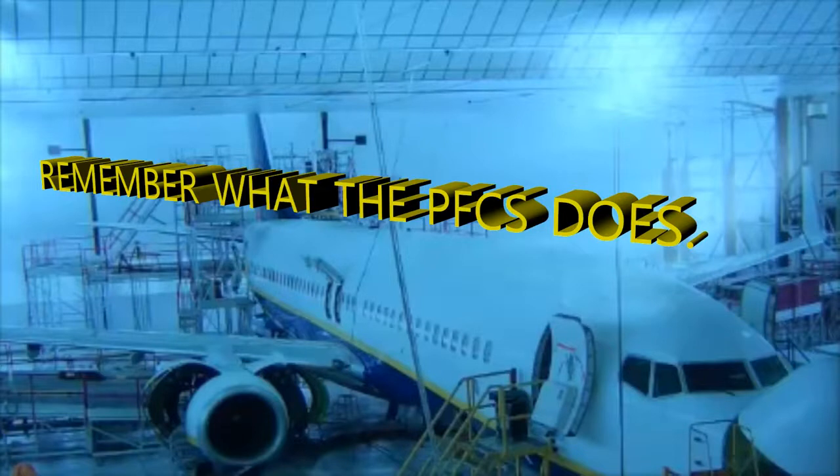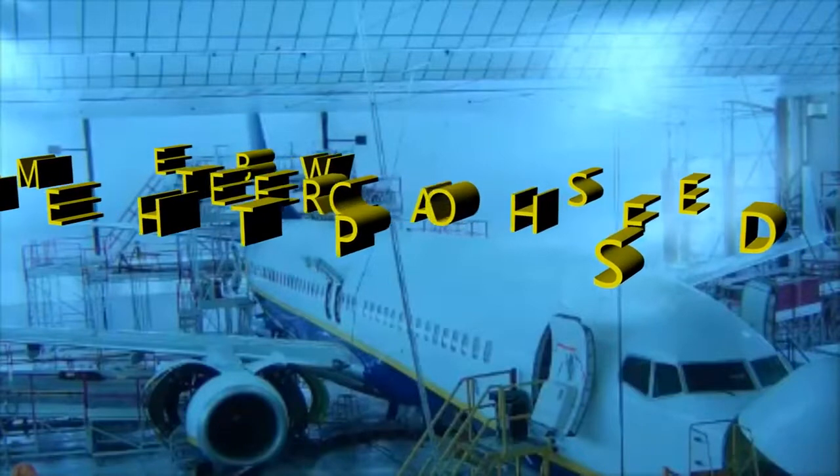You also have what's called a load alleviation function. That's not done by the secondary computers, by the way. That is strictly by the primary computers only. You also have the multifunction probes that send the data for the load alleviation function computation, and that goes to their respective Aileron and also to their respective primary computer.